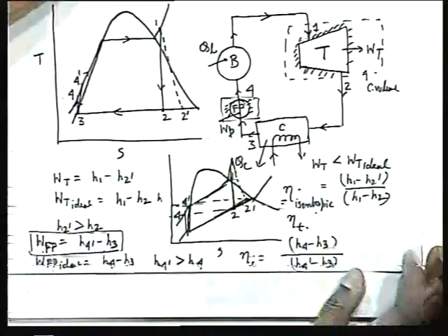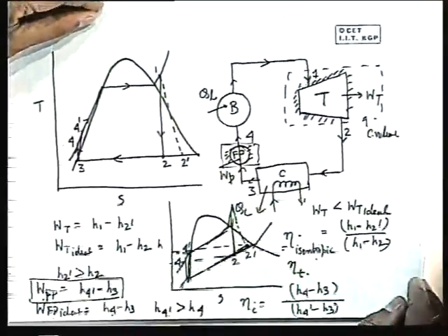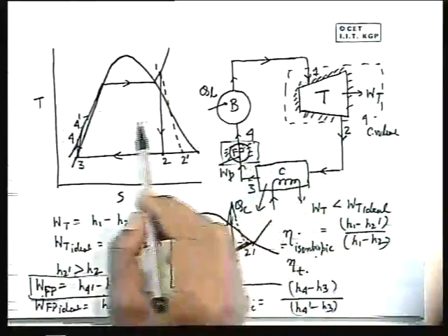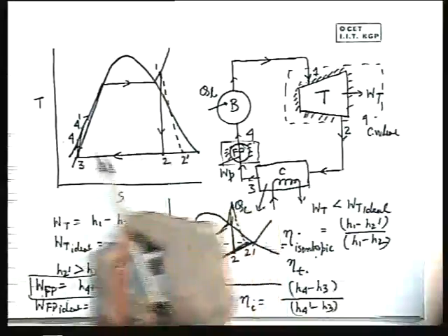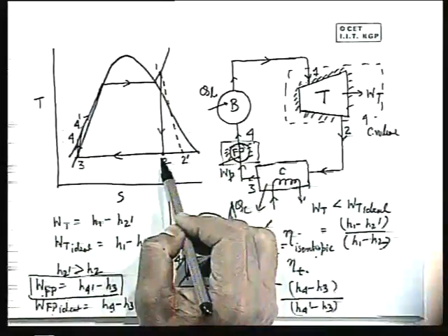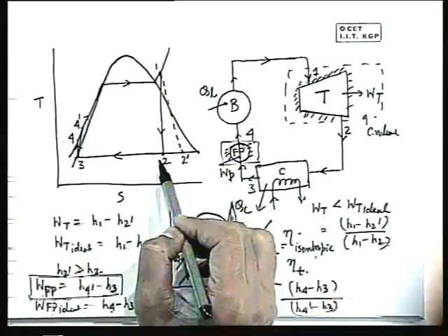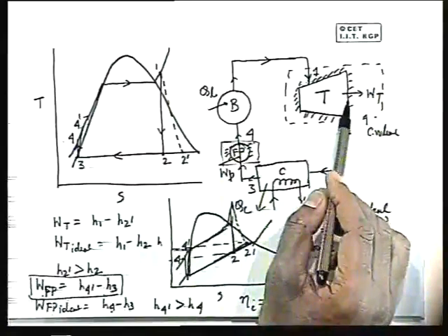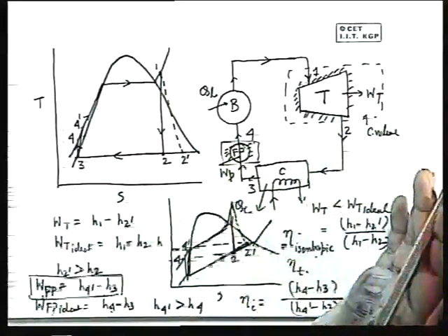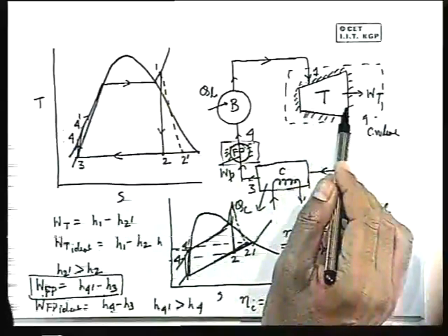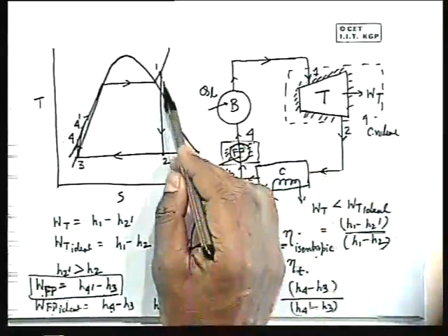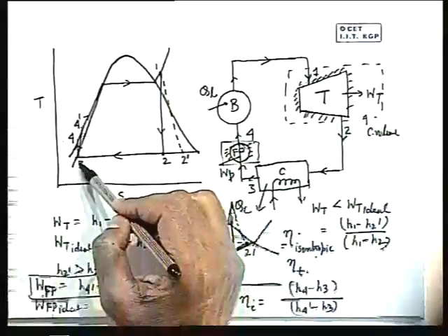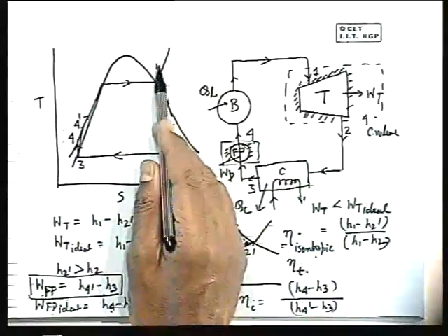All right. Now, there are other losses which are not that prominent as the losses in compressor, turbine and feed pump, because when you consider an isentropic process in feed pump and turbine, this is really a drastic assumption. It is too much a theoretical process, because no process can be accomplished without friction as the mechanical dissipative agent. So, friction has to be there, it is inevitable. So, therefore, there is a lot of irreversibility which makes the process irreversible. But other processes we can maintain as close as possible.